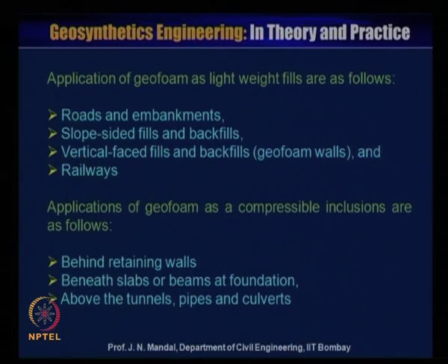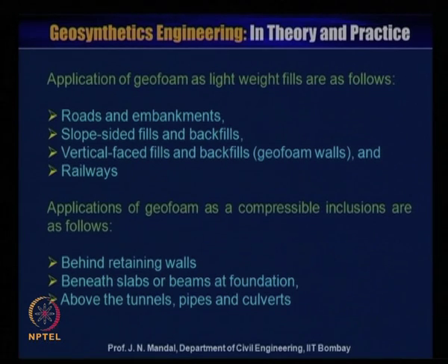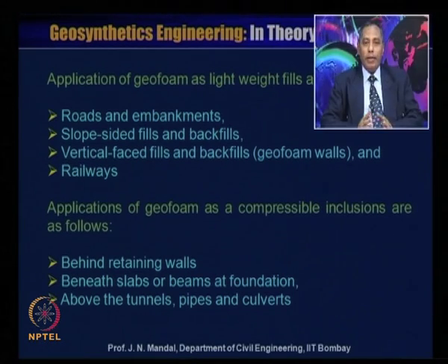Now, application of geofoam as a light fill is as follows: road and embankment, slope side fill and back fill, vertical face fill and back fill, geofoam wall and railway. Application of geofoam as a compressible inclusion is as follows: you can use it behind the retaining wall, beneath the slab or beam at foundation, above the tunnel, pipes and the culvert.